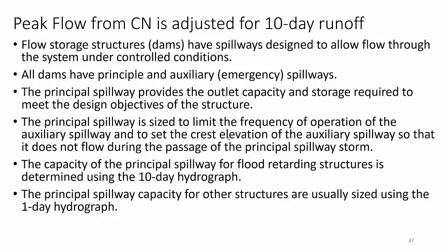It's there for emergencies. The capacity of the principal spillway for flood retarding structures is determined using the 10-day hydrograph for the design storm. It's usually a 100-year event. So the principal spillway capacity for other structures are usually designed for the 1-day hydrograph. So if you're doing principal spillways for non-reservoirs, then you use a 1-day hydrograph. But for flood retarding structures, we use a 10-day hydrograph because of this compounding long-term flow event.